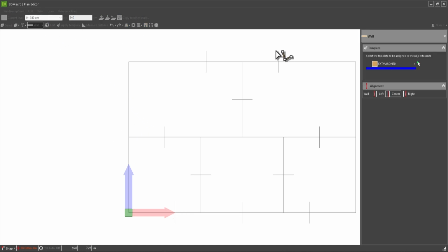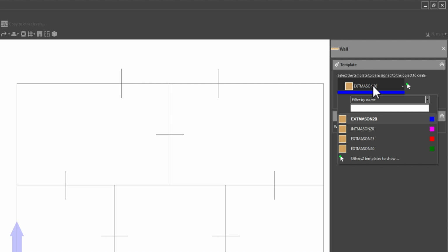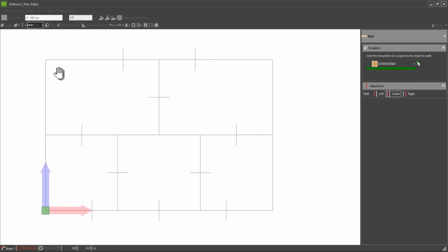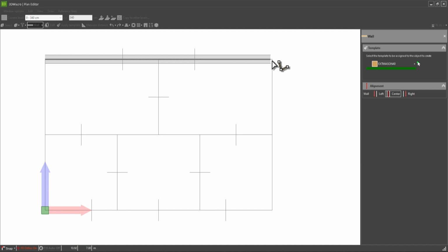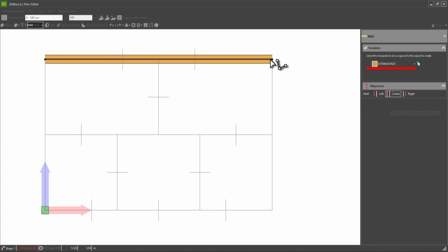Use the DXF drawing to draw the geometrical model and, in particular, draw the plan lines. Choose the element type, format and alignment, and draw the wall, relying on the previously imported reference line. To accurately draw the plan lines, use the graphic clips. The relative position between the footprint of the plan line and the fixed line is determined by the selected alignment, which can be all left, all right or centered with respect to the drawn fixed line.